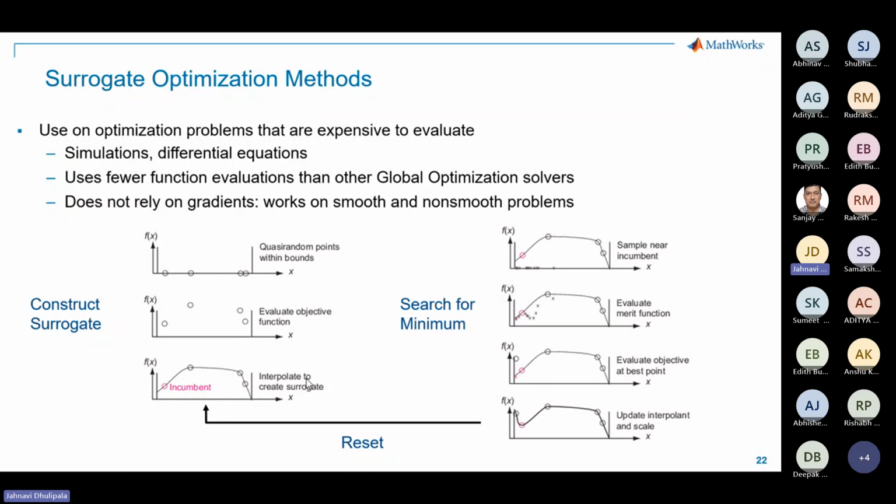And this technique is very promising for complex circuits, far more complex than the simple op-amp that we just saw today. We just took an op-amp as an example, and in that op-amp we took a couple of transistors, and we set up that I need to achieve this bandwidth, this is my gain and current, and I gave this input to the surrogate optimization method, ran the optimization algorithm, and then finally implemented that in the model.